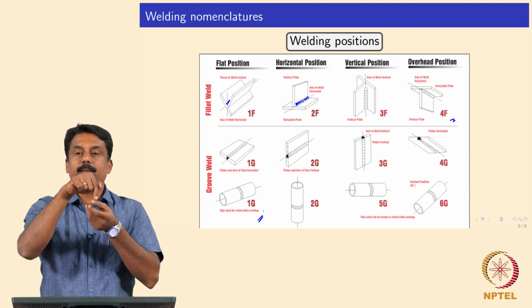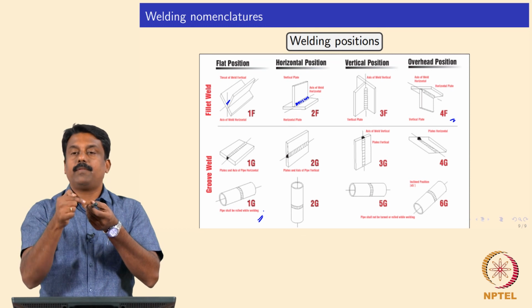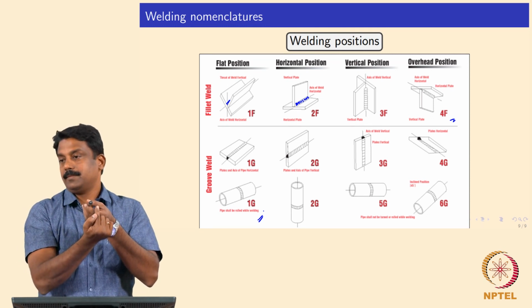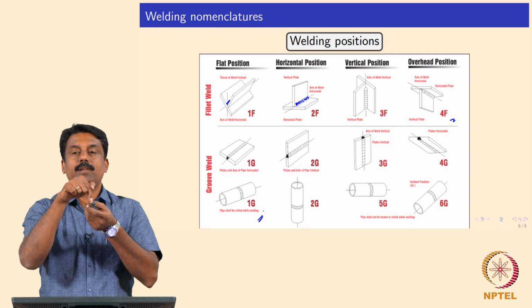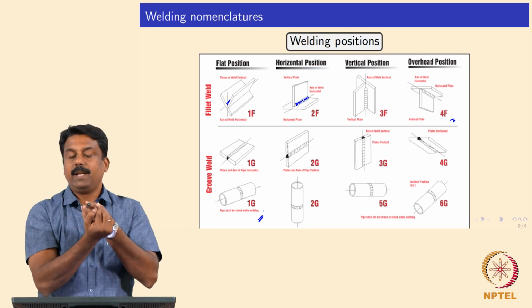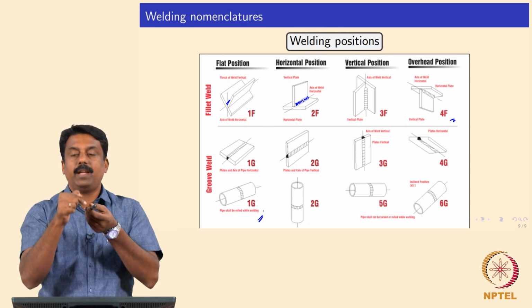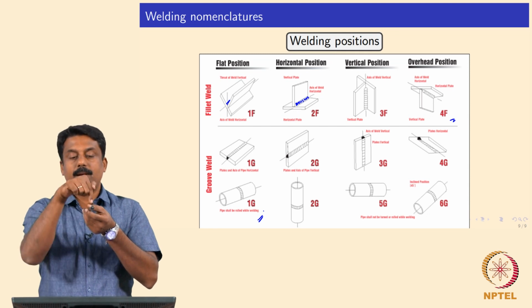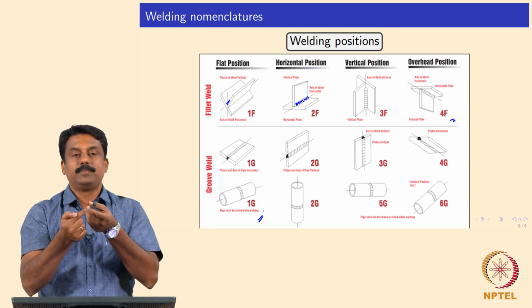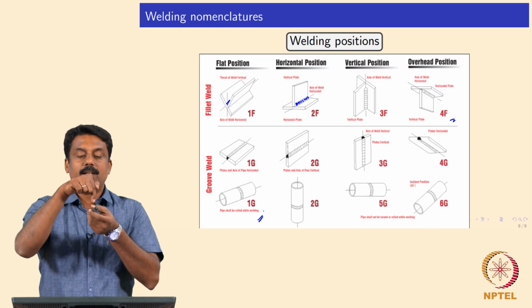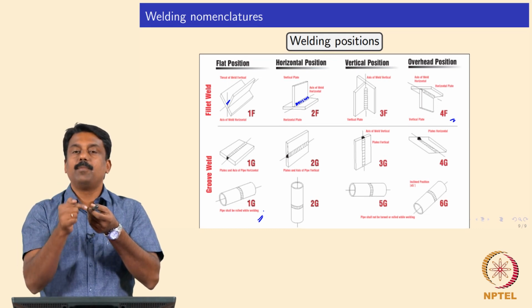So your welding program should be adaptive as a function of the position, so that you don't change the droplet transfer frequency as well as transfer behavior, because the balancing forces are always changing, isn't it? So that's why welding in 5G configuration is the most challenging.